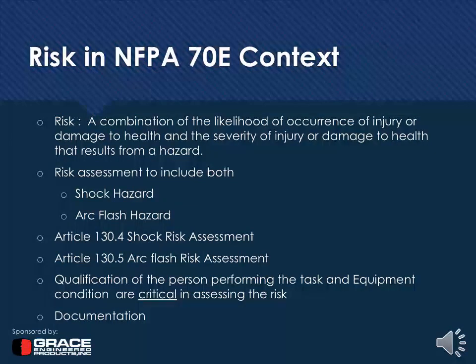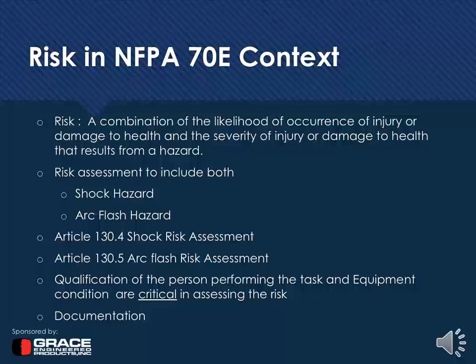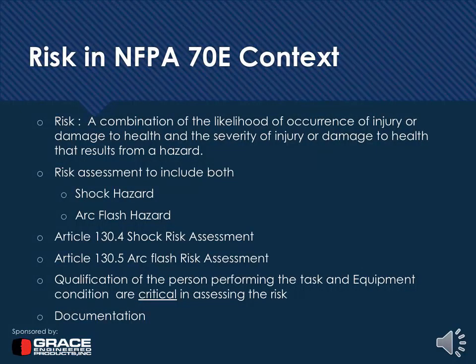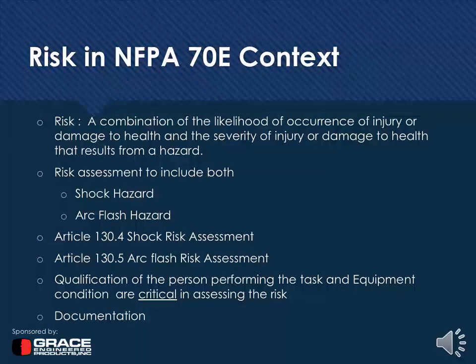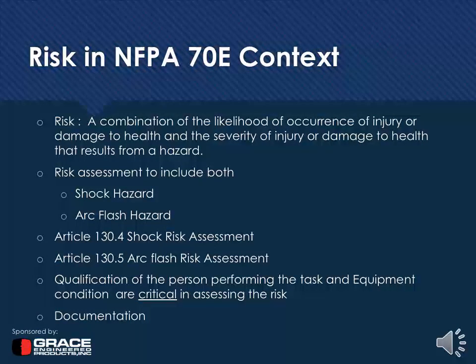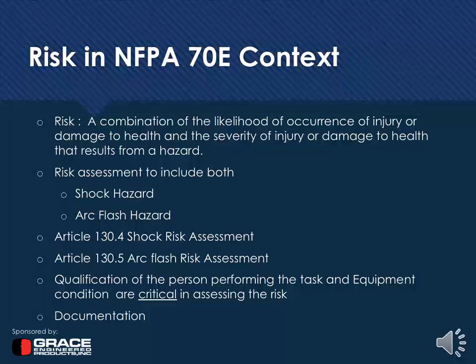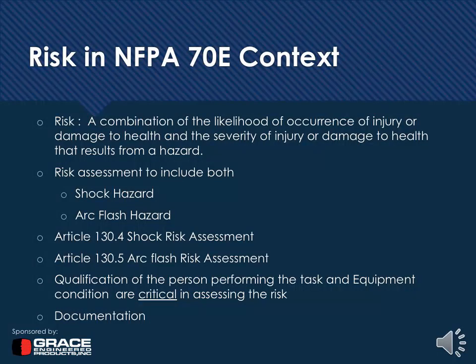So the next one is the arc flash assessment. When you look at the arc flash assessment, you need to understand the arc flash hazard likelihood and severity, and you need to also understand the arc flash boundary conditions, which John again mentioned, the distance at which the incident energy equals 1.2 cal per centimeter squared or 5 joules per centimeter squared. So arc flash PPE has to be used in accordance with 130.5G or 130.7C15. So there are two label methods which you can use. One is the incident energy calculation method, and the other one is the PPE category method. Just make sure that you can't use both on the same piece of equipment. You need to use either or. And also make sure that you use the additional protective measures that need to be used while doing the arc flash assessment as well.